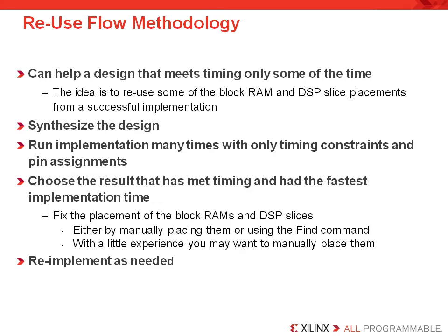The reuse flow can quickly help a design that meets timing only some of the time. The idea is to reuse some of the block RAM and DSP48 placement from a successful implementation run to seed a later run. This approach can be used when the design meets timing some of the time and the names and structures for the macros do not change. Now you can synthesize this design and run the implementation tool as many times as you like with only timing constraints and pin assignments. Then you can choose a result that has met timing and had the fastest implementation time. Try to fix the placement of block RAMs and DSP slices, and if required, try to re-implement the design.